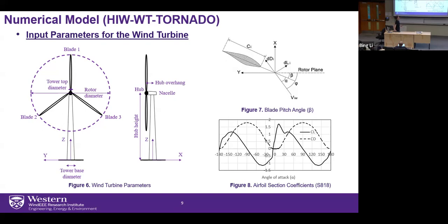And then the question becomes, how do you get the angle of attack? The angle of attack is defined by two angles. One is phi, the bigger angle, which is the attacking wind angle. And then beta is the pitch angle, because we're changing the pitch angle from 0 to 90. If we know the wind component, we can easily calculate this alpha.